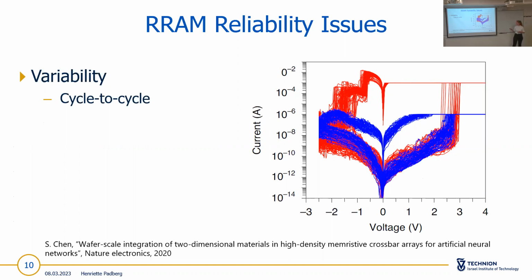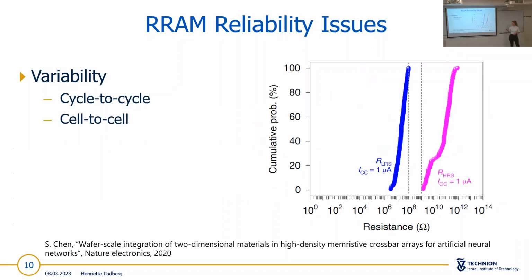Here the measurement was repeated for several cycles, and as you can see in the result, it shows a different behavior in each cycle, even though the measurement parameters were exactly the same. If you're wondering what the red graph is, that was just a measurement with another current compliance, but you can also see the cycle-to-cycle variability.